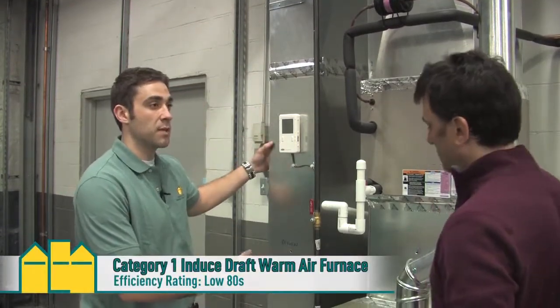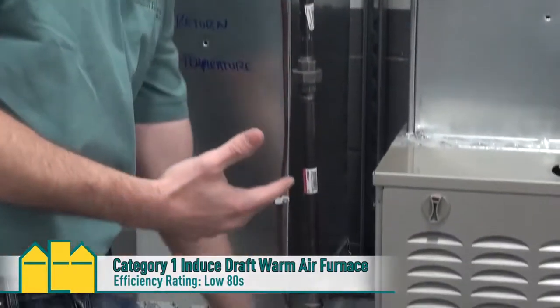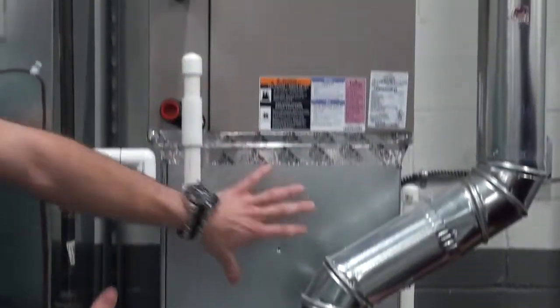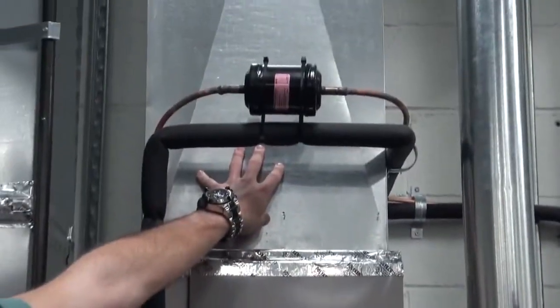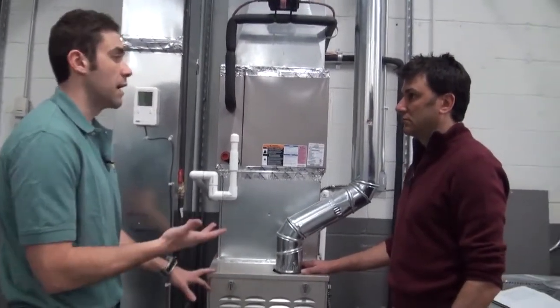All right, so here's some basic furnace anatomy. We have a typical warm air furnace. We have our return side, which brings air back from the apartment or from the home. That's coming down and being ducted into the side of the furnace. There's a blower motor at the bottom that's going to spin and cause negative pressure inside the return, and then it's going to push positive pressure through our supply. Coming off the top of the furnace, we have a supply transition, which transitions to our air conditioning coil, which then transitions to our supply ductwork. And that'll go off into the conditioned spaces and help heat or cool the home or the apartment. And this does both? This does both. This system is set up to do AC and heating.